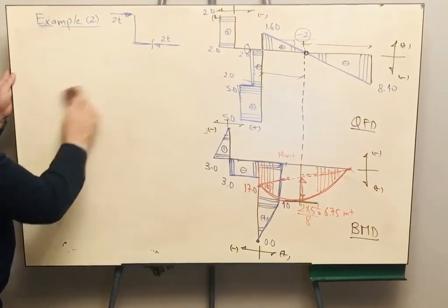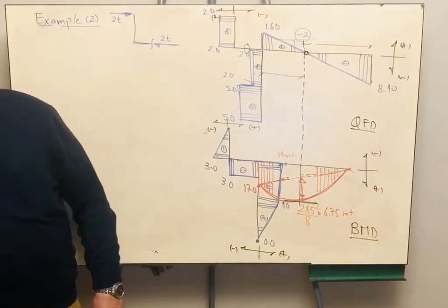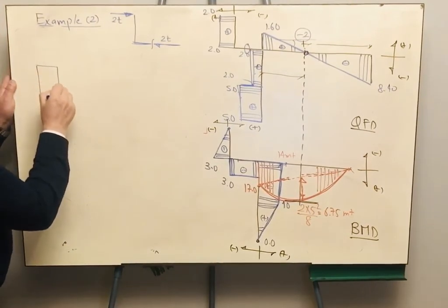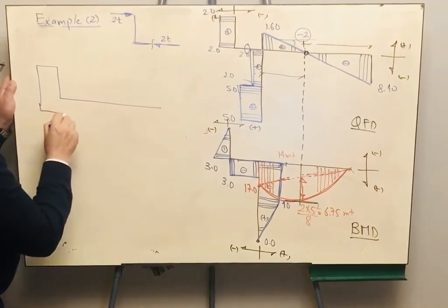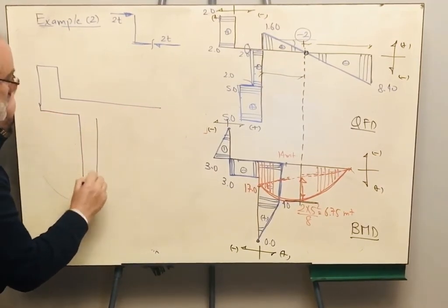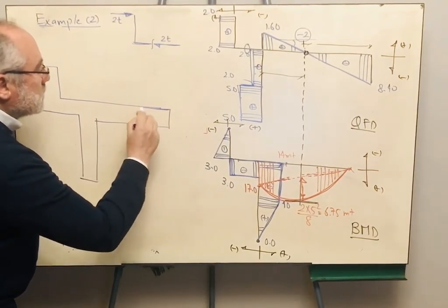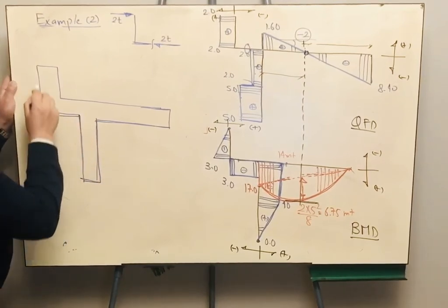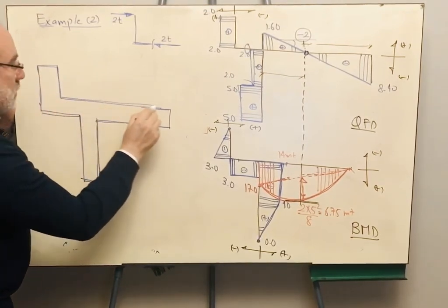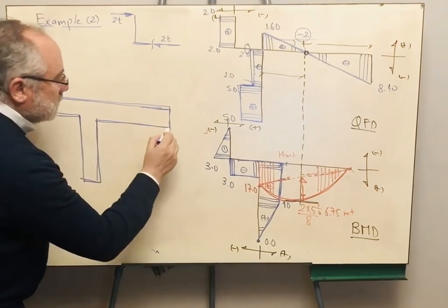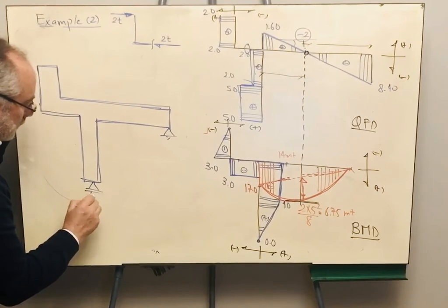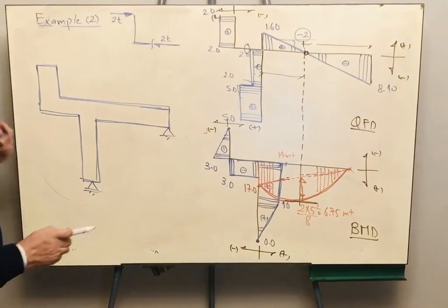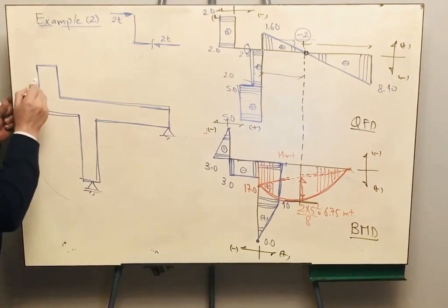If I want to see how they will reinforce the frame, then the frame, in real life, looks like this. Because we drew the bending moment, unlike 212, here on the tension side, and we know that the concrete is weak in tension, so it needs help, it needs steel reinforcement. The bending moment is drawn on the left. It means that we have cracks here.